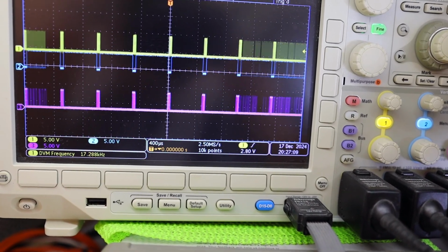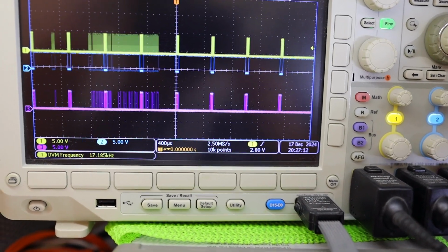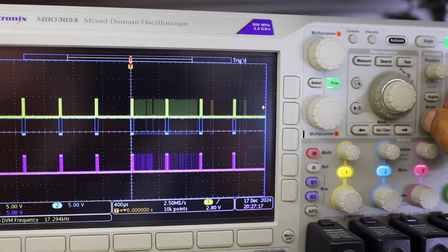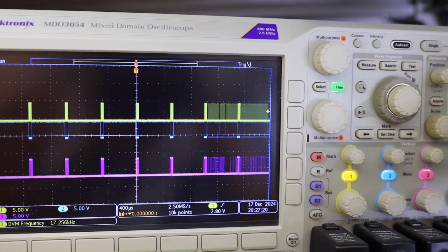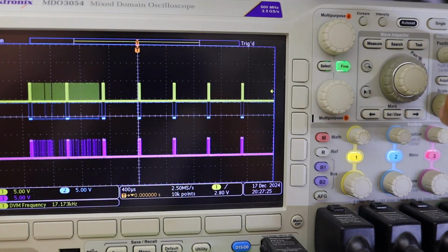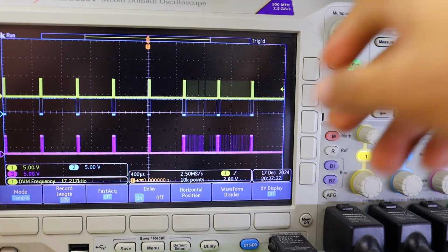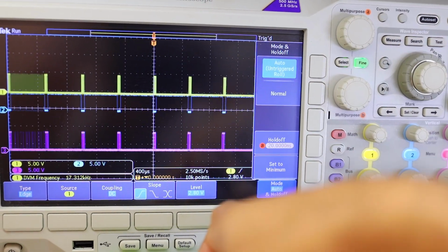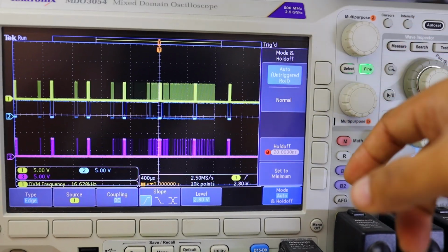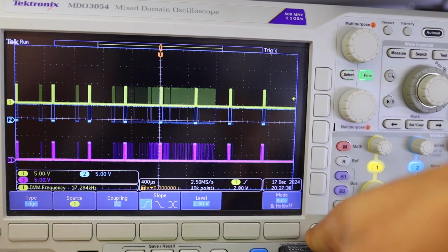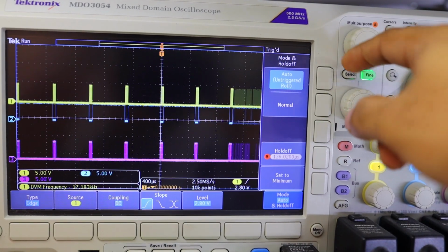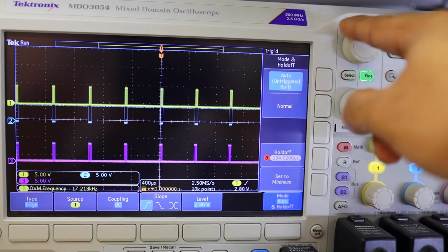Okay, so this is also one thing to catch, that not every oscilloscope is the same, and every oscilloscope does not react the same way. It may just be dependent on this feature. If you go to the acquisition menu, if you go to the trigger menu, then you have this hold off time set to, I believe, the minimum value. I cannot set it to less than 20 nanoseconds, so that's appropriate. If you set it to more than maybe a millisecond or something like that, you would not see your guy appearing all that much.